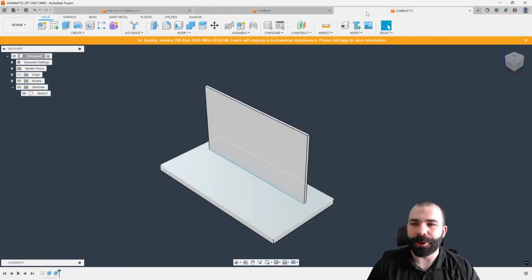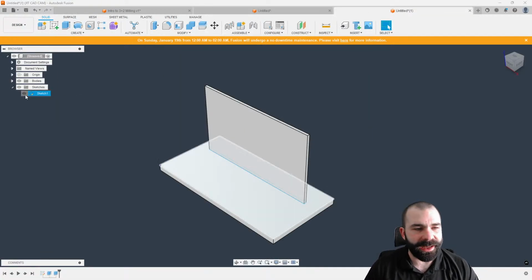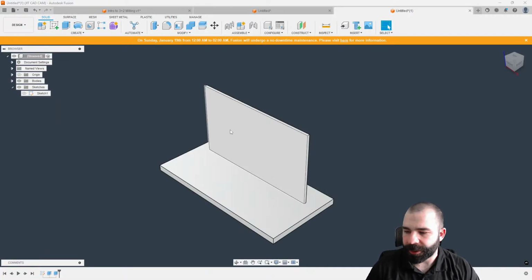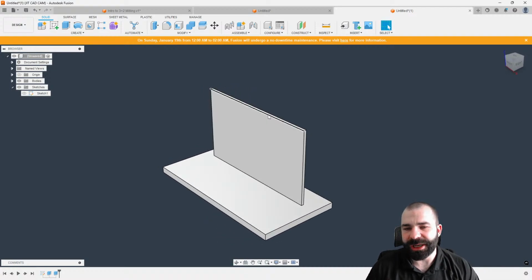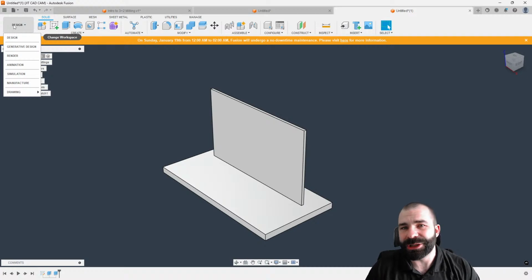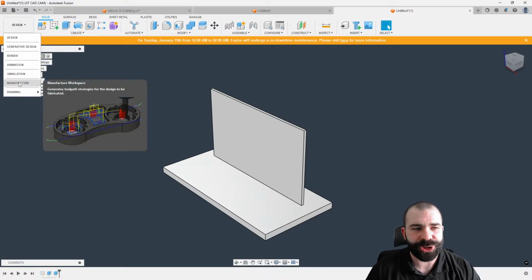Let's go ahead and jump over to where we were talking about doing something like a very thin wall part, right? So the question is how can I machine a thin walled part and avoid things like chatter? Well, there's a lot of ways you could do it, but on a part as simple as this, your system might need to do what I like to call a layer cake, right? Like we need to do it section by section, right?